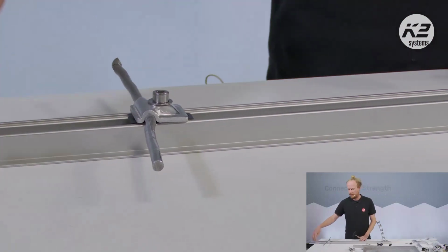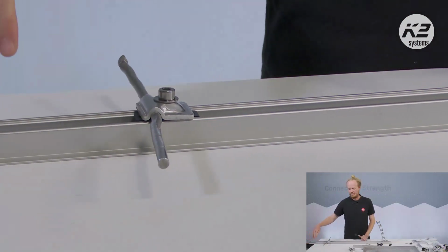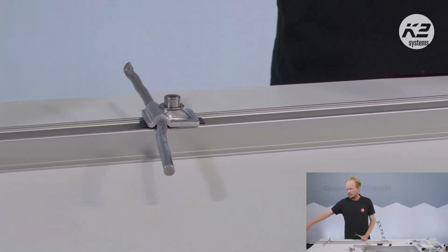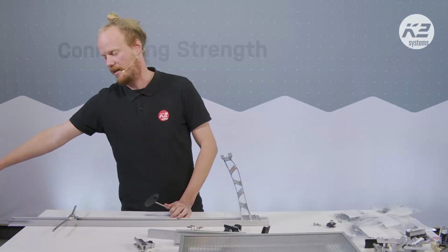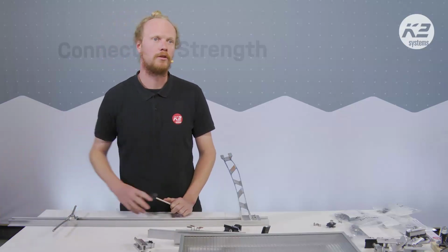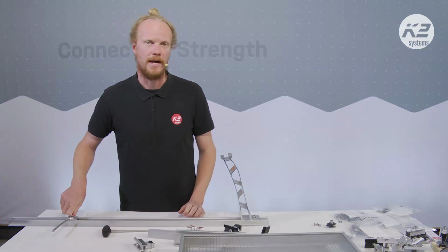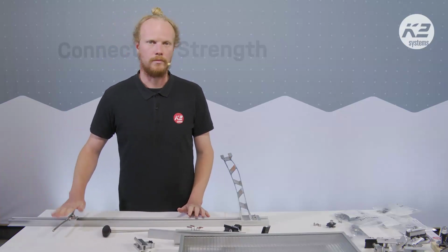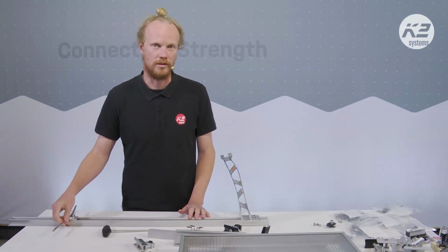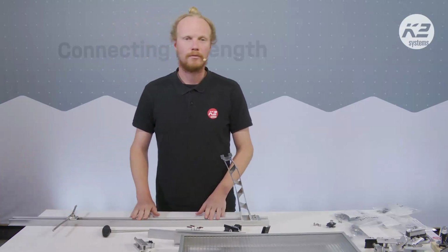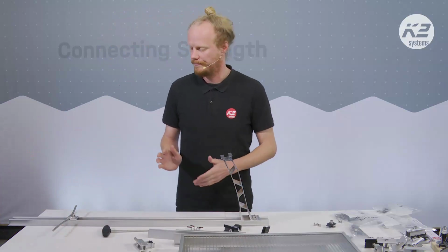If there is a rail running this way, this cable can be bent out and connected to a next rail, or a perpendicular rail. The options are quite wide with what you can do and how you can do it with the lightning protection set and the cable that's involved with that. Not just for flat roofs, but also for pitched roofs as well.